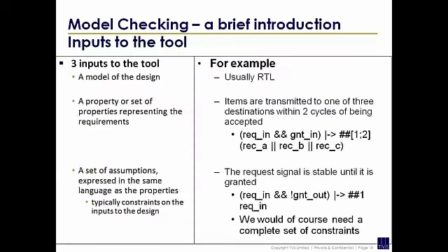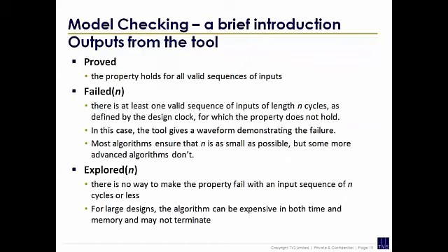And what will happen is you say that got proved. I've proved that property. It's a fantastic result. I've now got a proven property. It failed. Failed could be one of 2 things. Either you found a bug because the design doesn't satisfy the property which you're trying to prove, or you're under constrained, and you found a bug here in the illegal space rather than the legal space.